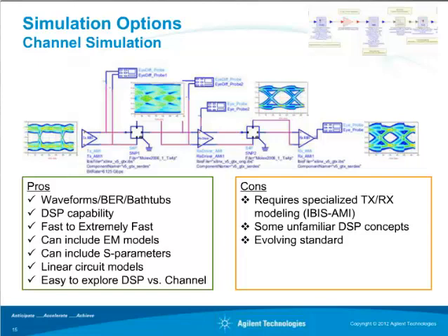On the downside, well, yes, there's certainly the need here for specialized models of the transmitters and receivers, and they're called IBIS AMI models, and we'll talk about that in a moment. And for some of us, if you're a circuit designer, you may not be familiar with some of the DSP concepts. But again, it's not an open DSP. The DSP is really put into the simulation by a modeler, somebody who's produced the transmit and receive models, and you'll see that later on. And one other thing is this is an evolving standard, and it's evolving in a positive direction, which is the good news. So you will have to keep up with the changes, and I'll discuss some of the things we're looking at there in terms of the future.